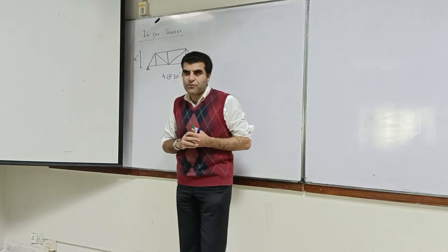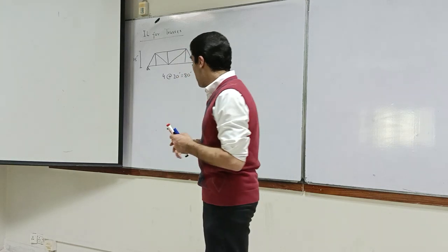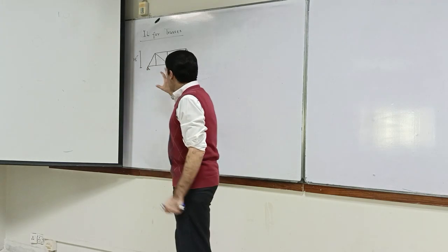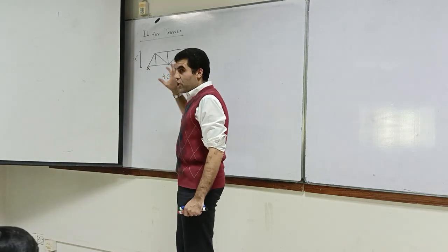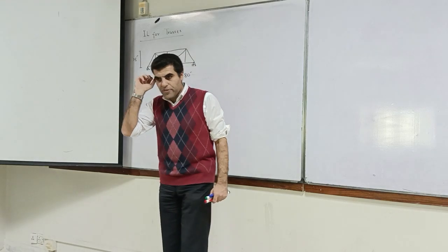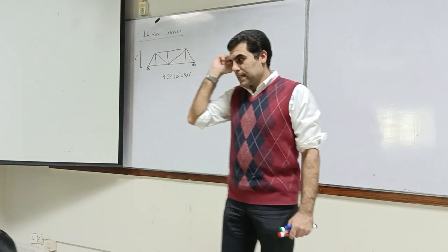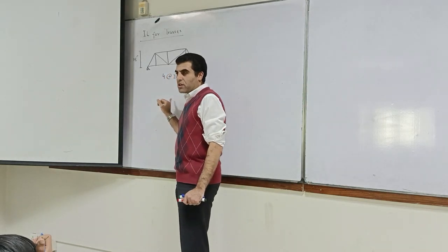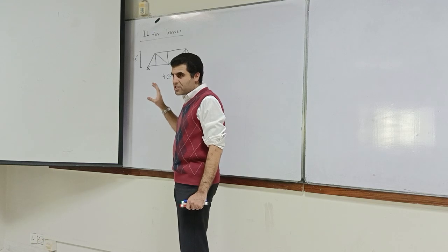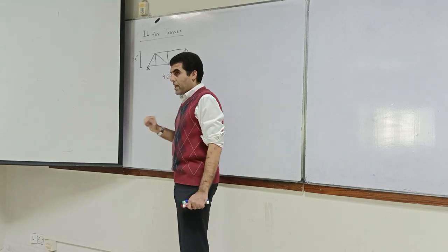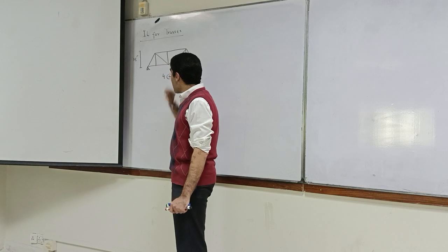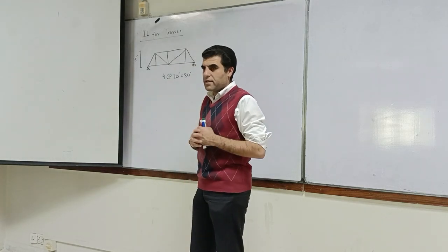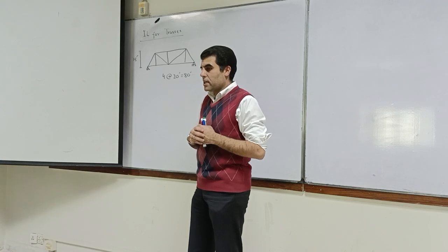draw the influence line for beams, depending on our variable of interest. In case of trusses, you can use the Müller-Breslau principle, but the problem is that it becomes mathematically too involved. So therefore, it's not normally used. The principle is not normally used for trusses. We can use, like from the first principle, we normally find out the influence lines for trusses.